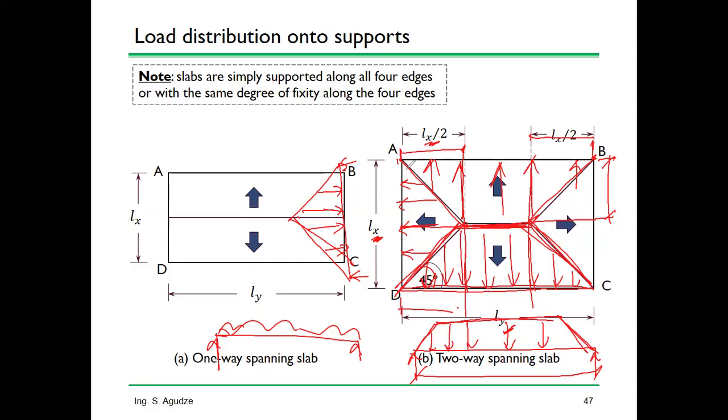What we are saying here is that we call something yield line. We are saying if this slab is to fail, if we put heavy load on the slab, the crack pattern in the slab will look like this. That's the kind of analogy we are using to say this is how much load goes to this and goes to that. In a similar way, for simply supported, the crack pattern will be like this. And half of this will fall on this beam.